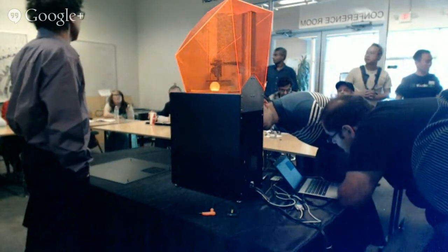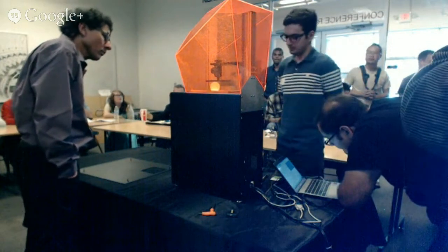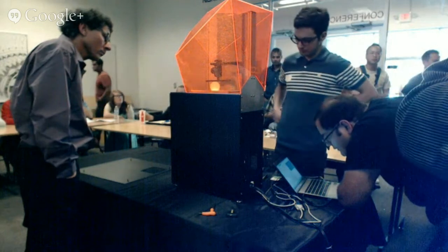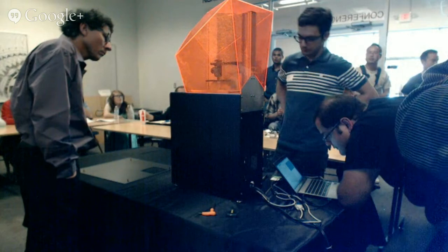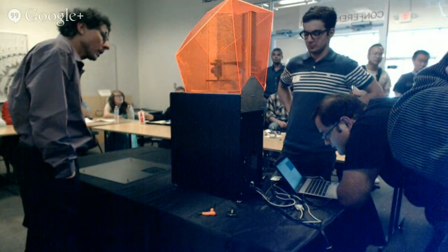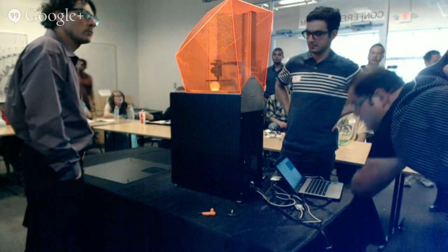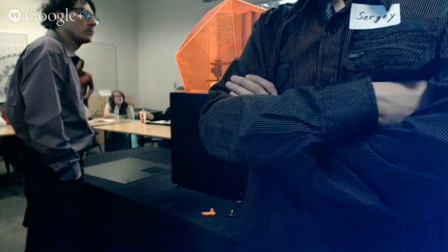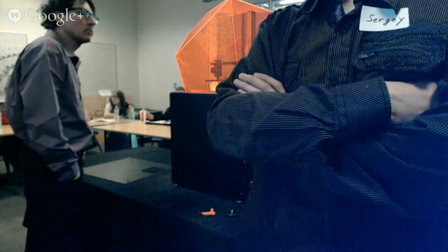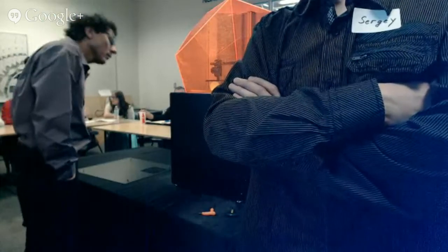But my window there is oftentimes much bigger, meaning if the resin, say, takes 3.5 seconds to cure a layer, if I go to 6 seconds, 8 seconds, not a huge difference. If I go to 14, 15, yeah, it's going to get hard to release. I'll notice it, right? But I have quite a big, like 100% exposure time leeway on film. Silicone, every extra 1/10 of a second takes your life down, right? You just want to minimize the amount of extra exposure because all of that consumes your vat life.